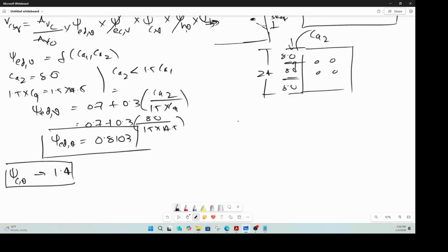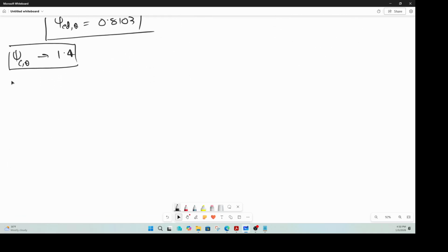We already saw that in the code, right? Now the only thing left is to calculate your Vb value, which is the basic strength. Again, for Vb we have two formulas. One is 7 times (le divided by the anchor diameter) to the power 0.2, times the square root of the anchor diameter,